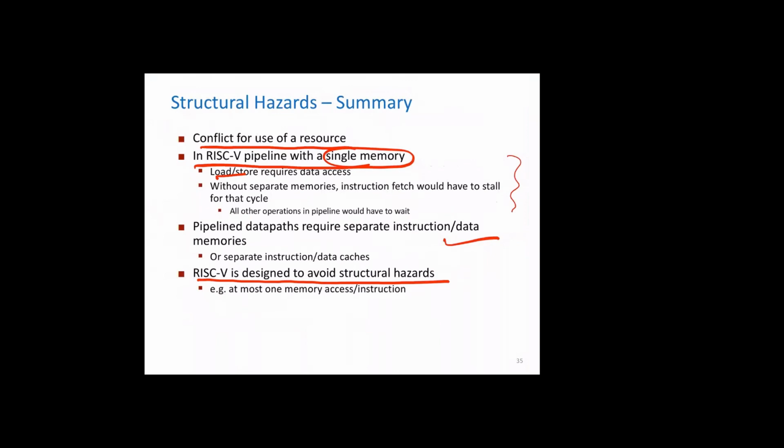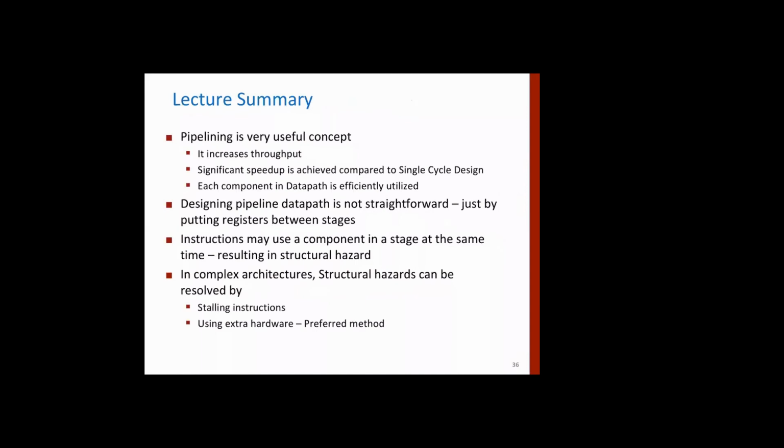And second thing is that instructions can move sequentially, and different parts of an instruction can be executed in a pipeline manner. But at the same time, note that when we generate control signals for the first section, those control signals also need to be carried along till the end, until they are exhausted or used.